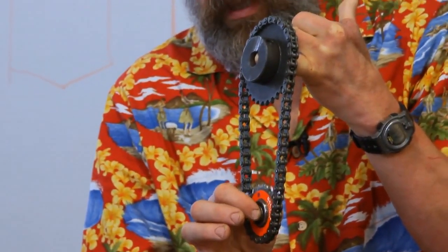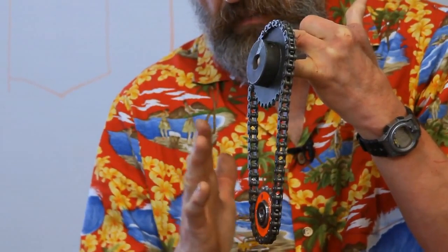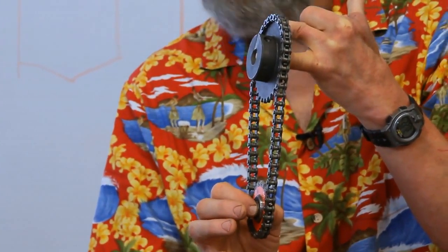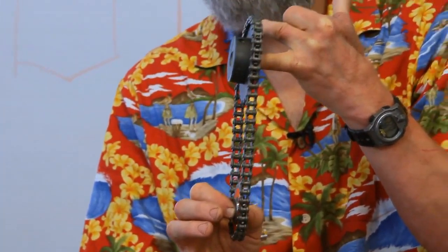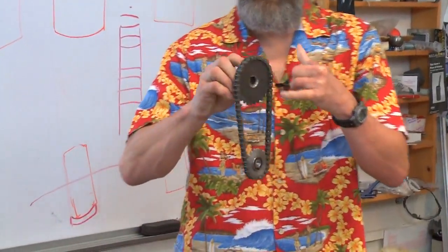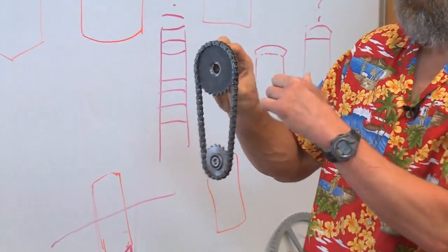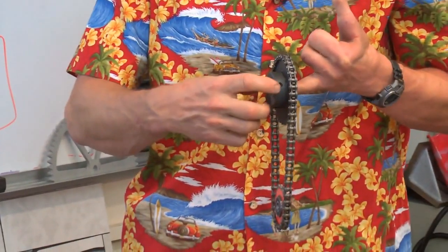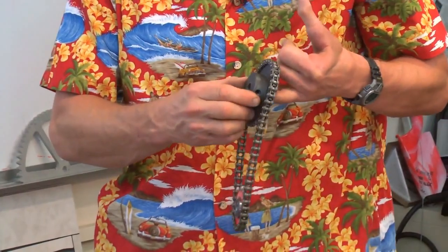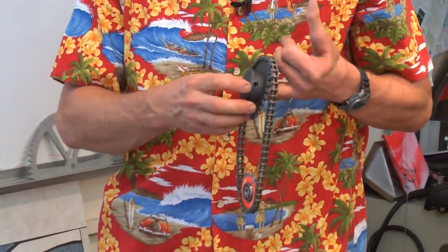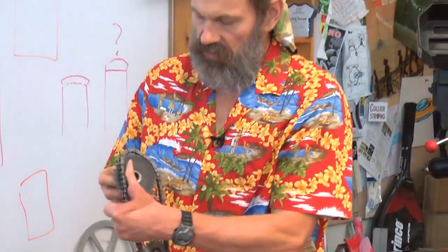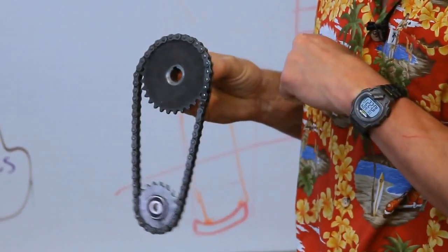You put a ball bearing in there that is not stiff in angular motion, so it'll give you some misalignment capability just inherent in the bearing itself. Meanwhile, on the drive sprocket, notice you've got this hub that gives you a space to, in this case, a set screw goes, and it's not the set screw that transmits the torque. The set screw holds the key in place, which is what would transmit the torque to the shaft.